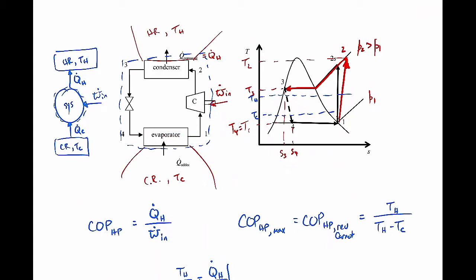Now, we have to manipulate the working fluid to move the energy around. For example, you have to pump it through the cycle. So the compressor does some of that. It pumps it around. So it takes some energy to do that. In addition, you have to make sure the heat transfers in the right directions at the evaporator and condenser. So here you have to make sure that you have the working fluid really cold. Here you have to make sure it's really hot. So the compressor does some work to make that happen.